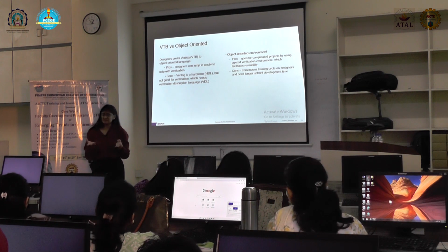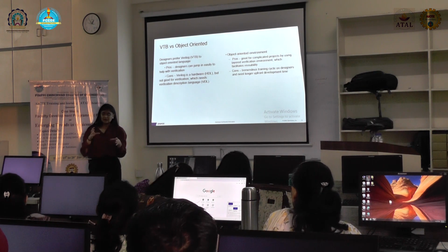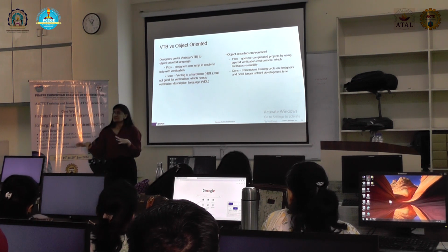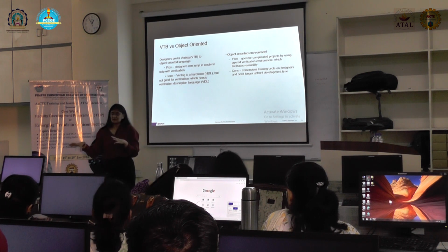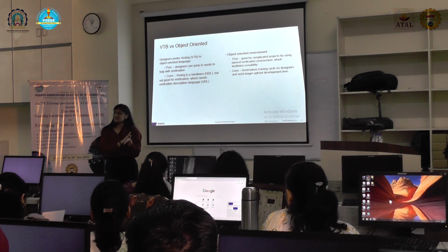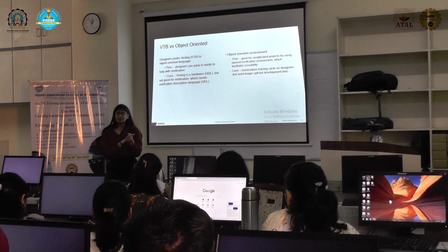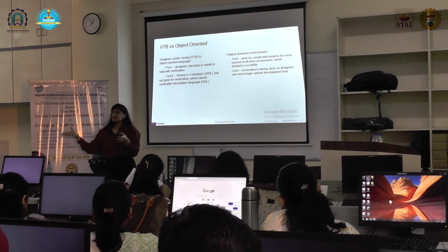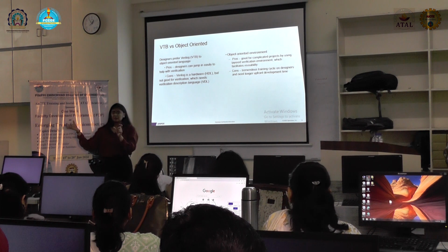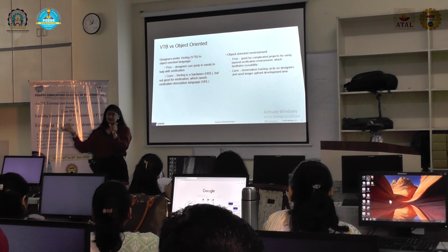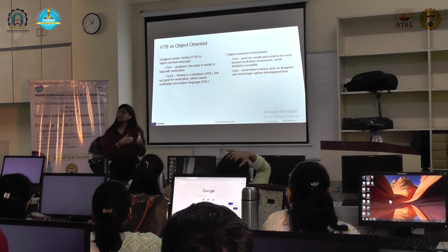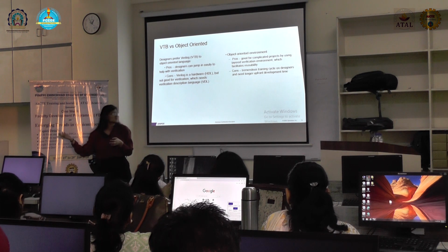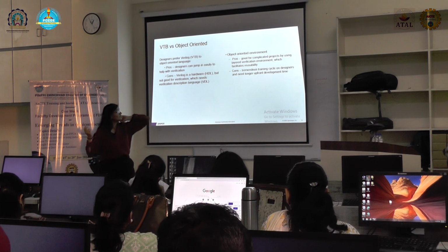No more than 5 or 10 minutes, I would say, is required for a small block to verify or create a test bench for a specific feature completion. The effort to create a very long test bench is less compared to the full-blown verification test bench. So if we don't have specific features or test cases ready while the designer is designing a specific module, they can have their own very long test bench, target that particular feature, and verify it prior to the verification process. So that is the purpose for which we can use it.